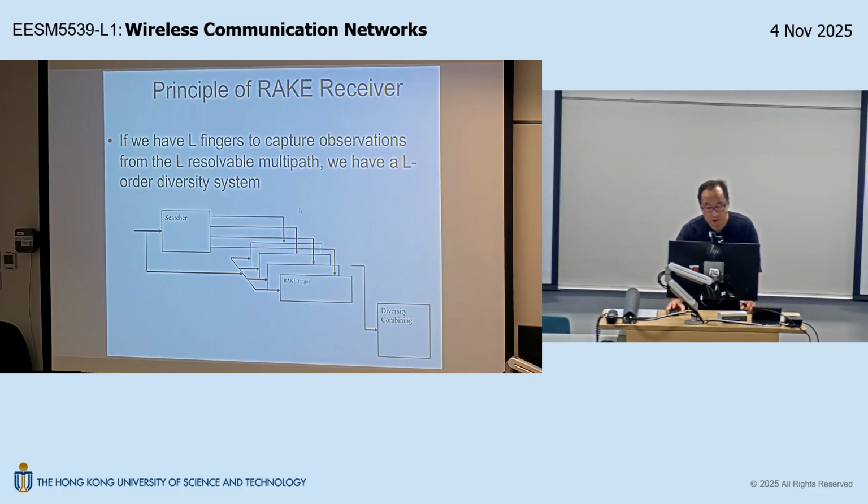Okay. So last time I haven't talked about how you know where. For successful despreading, we need to know two things. One is the despreading code, and last time I explained that in all CDMA systems, there will be an explicit signaling arrangement to tell the receiver what spreading code is used by the transmitter. So the knowledge of the spreading code is usually obtained through explicit signaling. But what about the despreading timing? The despreading timing is tricky because even the base station does not know about it. It is you, and the despreading timing depends on your current location as well, right?